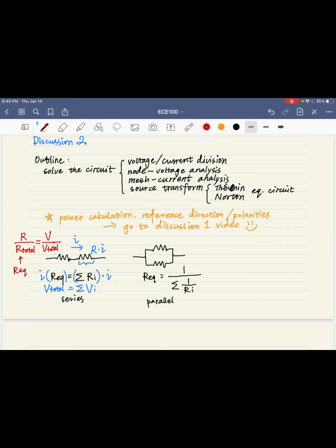And similar things happen for resistances in parallel. But the difference is that the variable they share is not current, it is voltage now. And we know I is equal to V over resistance. And 1 over resistance, 1 over R, is also called conductance, represented by the symbol G. So it can also be written as G times V. So pretty similar.